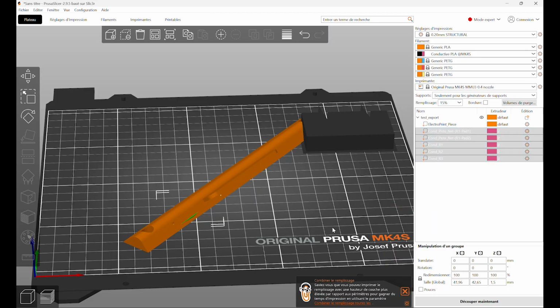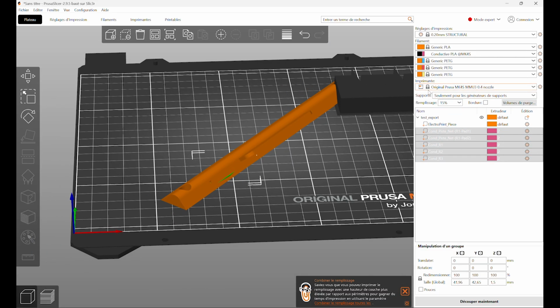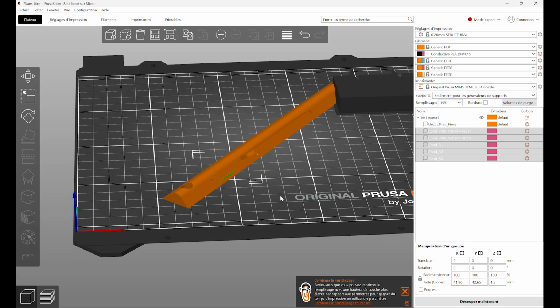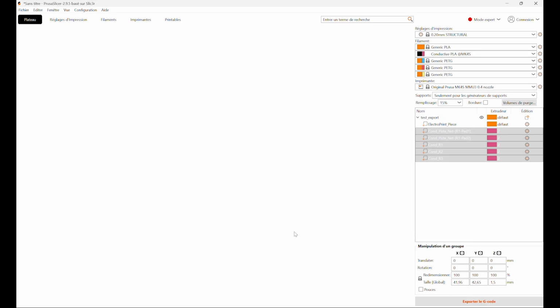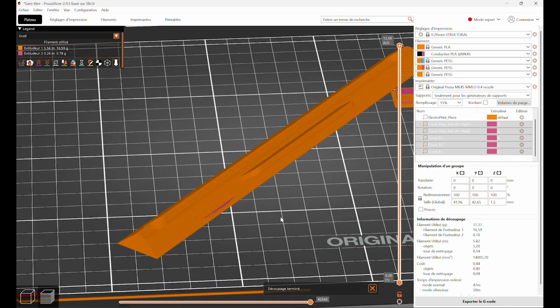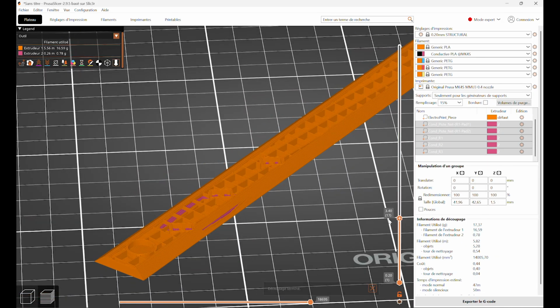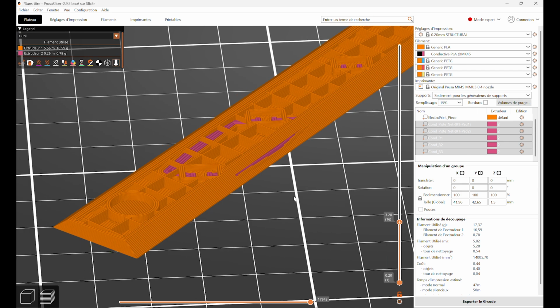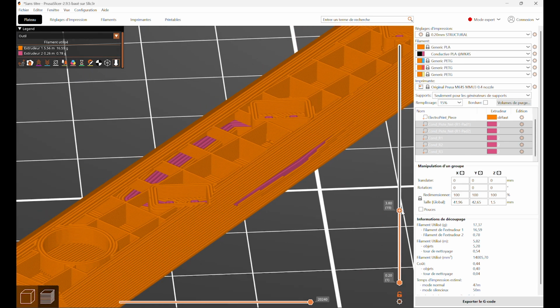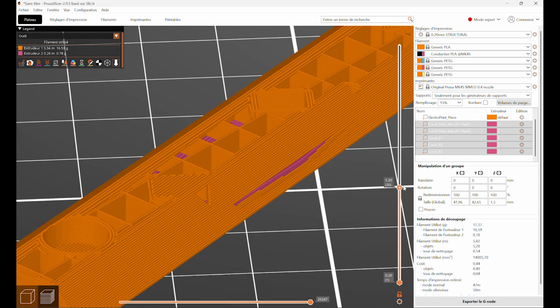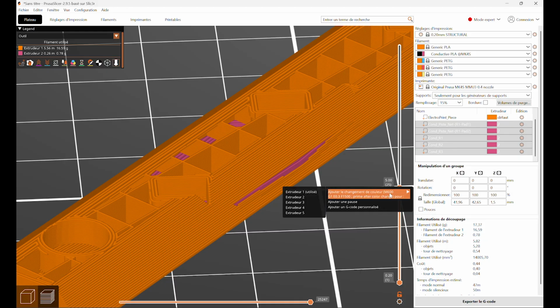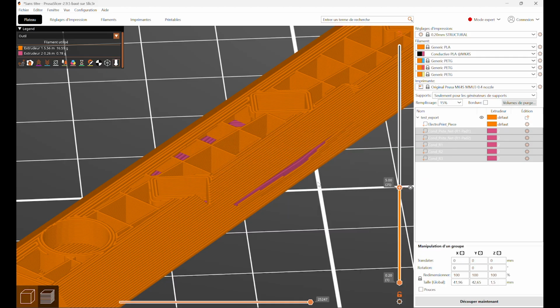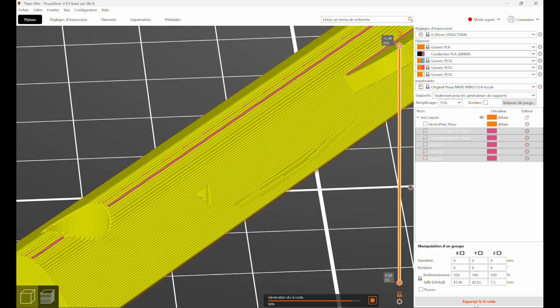Be sure not to use the function to add support everywhere. Do a first slicing. You will see that the cavities are ready to receive a component, and the tracks appear properly. You just need to add the pauses at the right layers. So you will be able to insert the components during the print with the old reliable print and place method. Reslice and let's go!